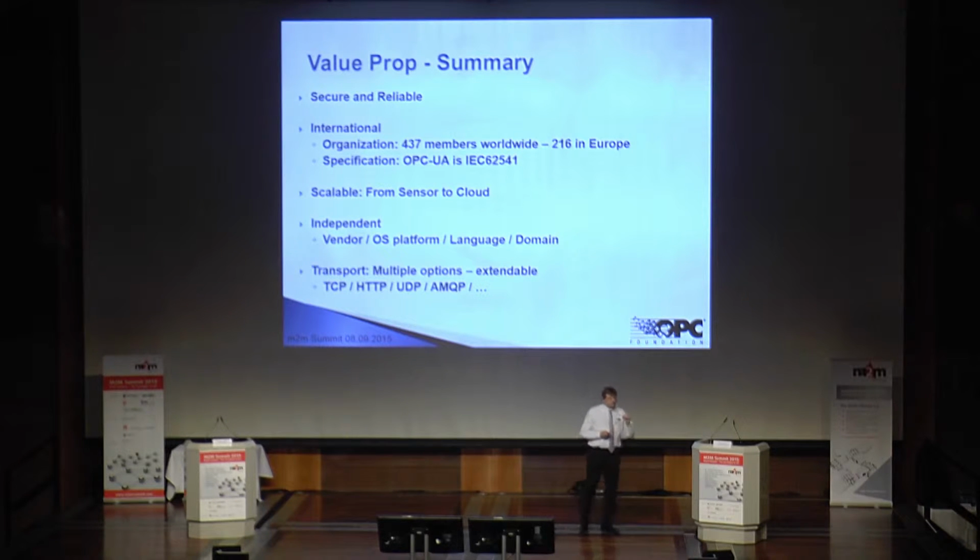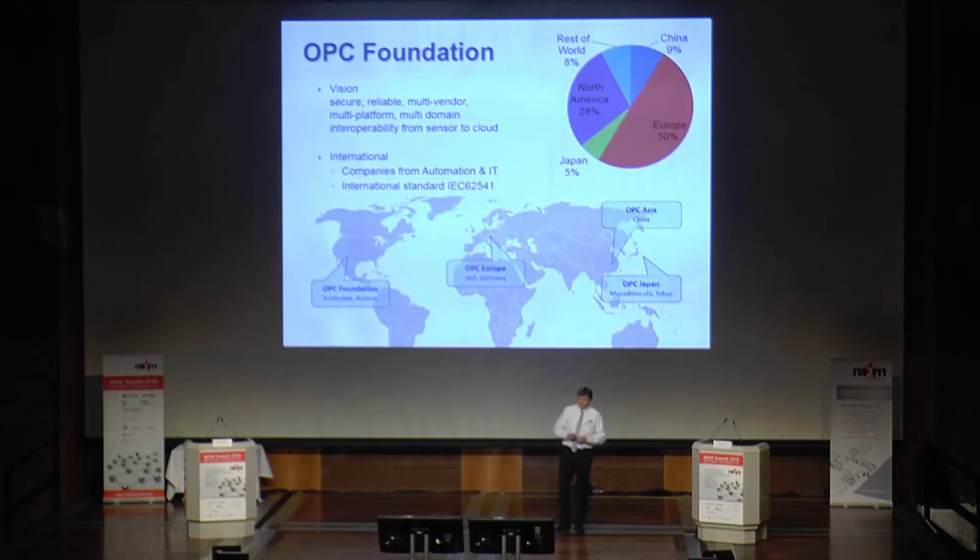And we are not talking about a protocol. OPC UA is not a protocol, then it would be Unified Protocol. The name is Unified Architecture, which means the underlying levels have the real physical protocol, and this is today TCP and HTTP. It is becoming UDP till the end of this year, and beginning next year, even AMQP. And if I see outside, well, MQTT or other protocols are popular, there's no blocking mechanism to also include that.